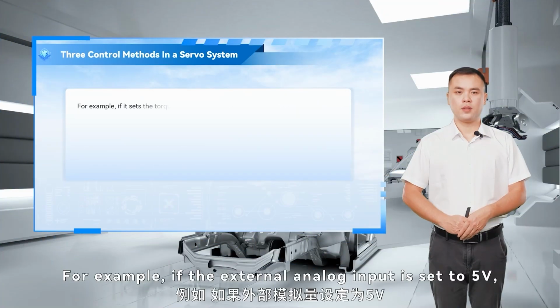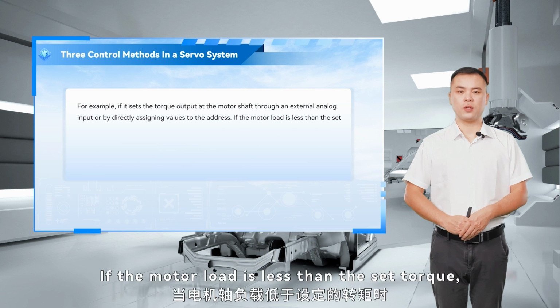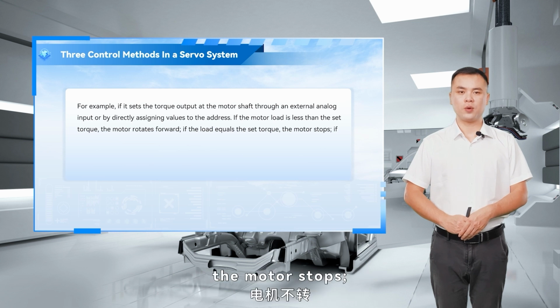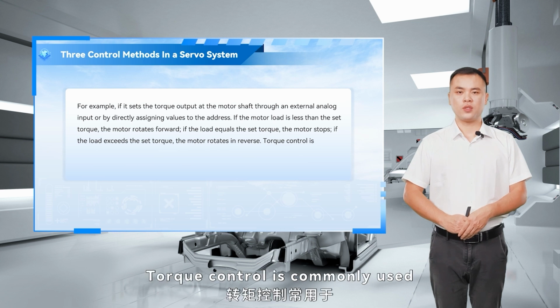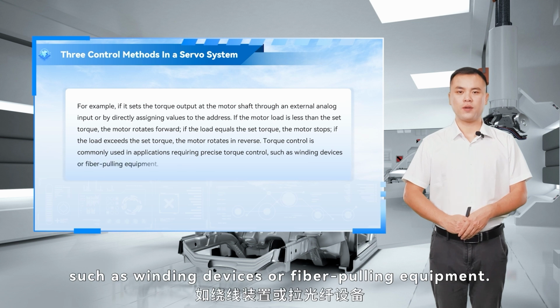For example, if the external analog input is set to 5 volts, the motor shaft outputs 2.5 Newton meters. If the motor load is less than the set torque, the motor rotates forward. If the load equals the set torque, the motor stops. If the load exceeds the set torque, the motor rotates in reverse. Torque control is commonly used in applications requiring precise torque control, such as winding devices or fiber pulling equipment.